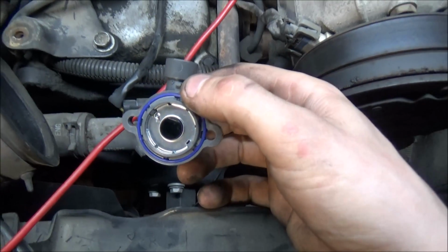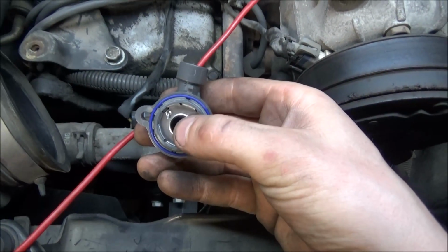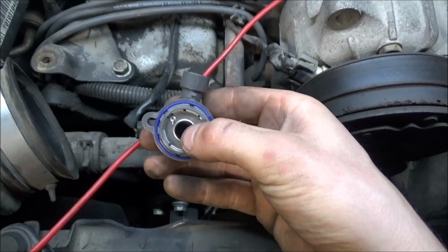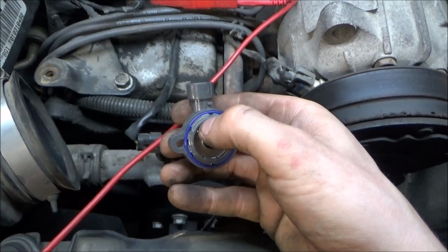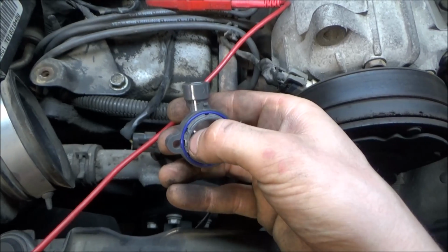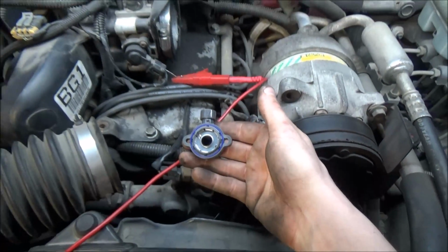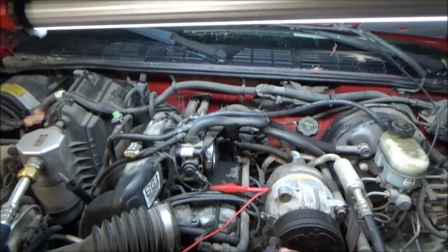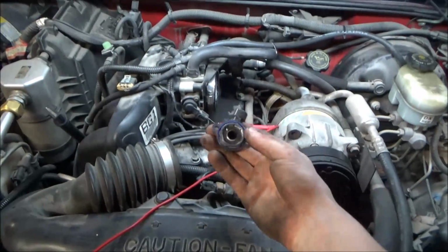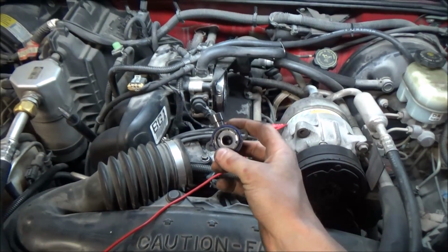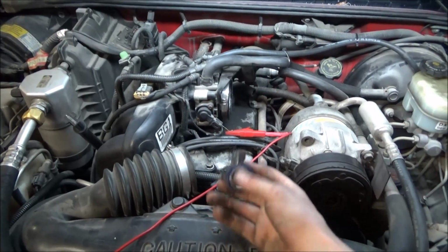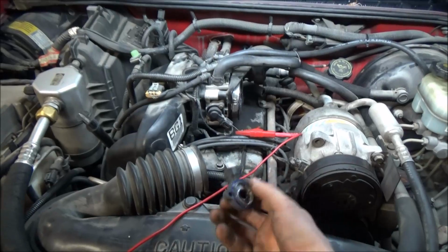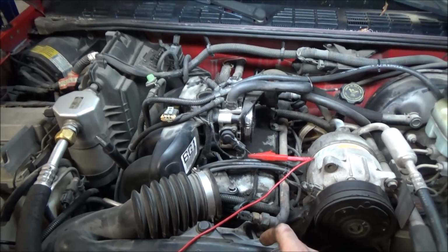But if we look inside of this unit, there's basically a little place where a shaft coming off of the throttle plate hooks into, and that shaft is going to rotate, and it drives a little lever inside of this unit, and that lever sweeps across a variable resistor, and that's what's going to basically signal the engine computer as far as where this throttle plate really is, you know, living. So that's kind of all there is to it, guys. But what we're going to do is replace this, and then we're going to show the fix after this.